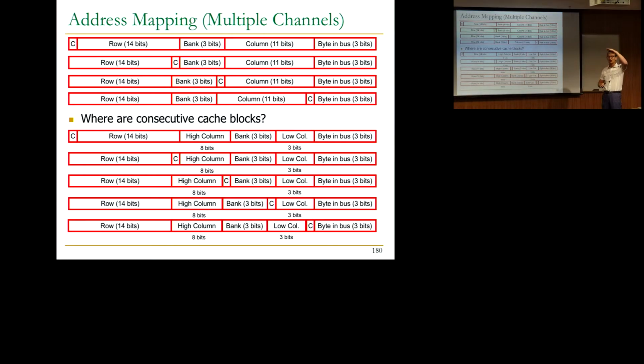So you're really partitioning your memory. Half of it, from 0 to half, is mapped here. From that half to the top is mapped here. So now your conflict patterns are determined based on that. If your memory is allocated such that you're only using half of your memory, now you're using only one channel. Basically, you wasted the other channel if you're not aware of that mapping. So that's one example. That's why usually channel bits are selected here.